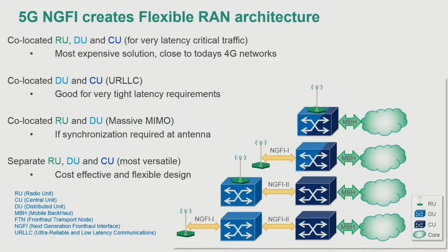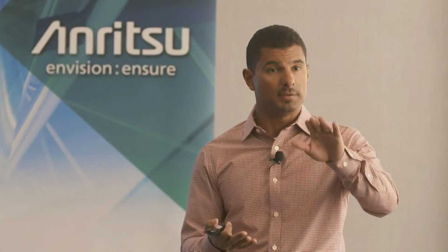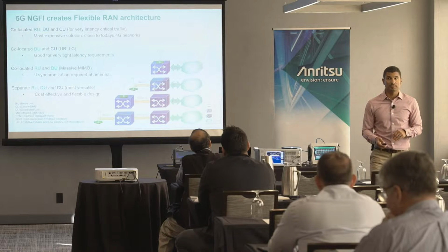How does this differ from 4G? In 4G with CPRI, you had no flexibility. CPRI was like a circuit. Once it was there, it was always transmitting. Whether there was anything in the antenna containers or not, it was always on. It always had the same latency. It was always very reliable because it was circuit-based. It was always synchronized. But what happens when you get higher bandwidth? You didn't get more IP data. You added more bandwidth, but your efficiency remained the same. This gives you the flexibility of differentiating those services.